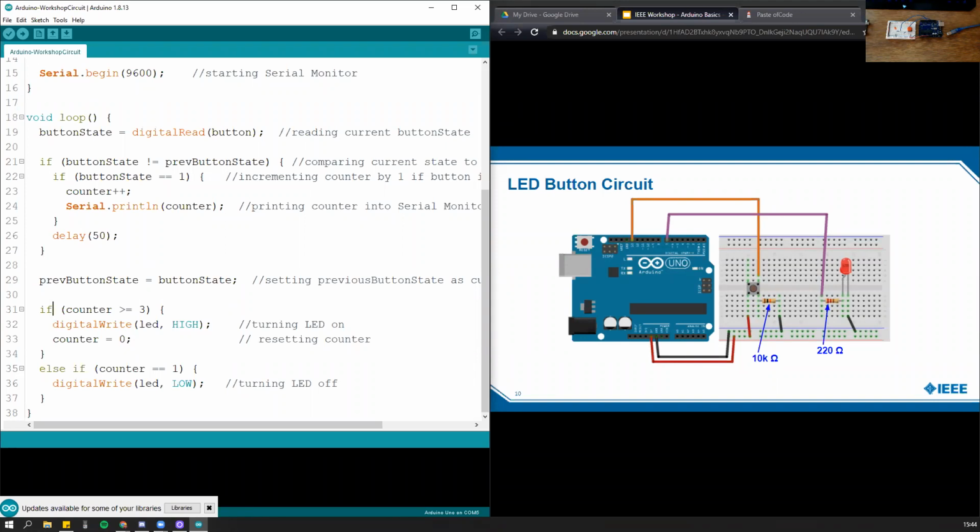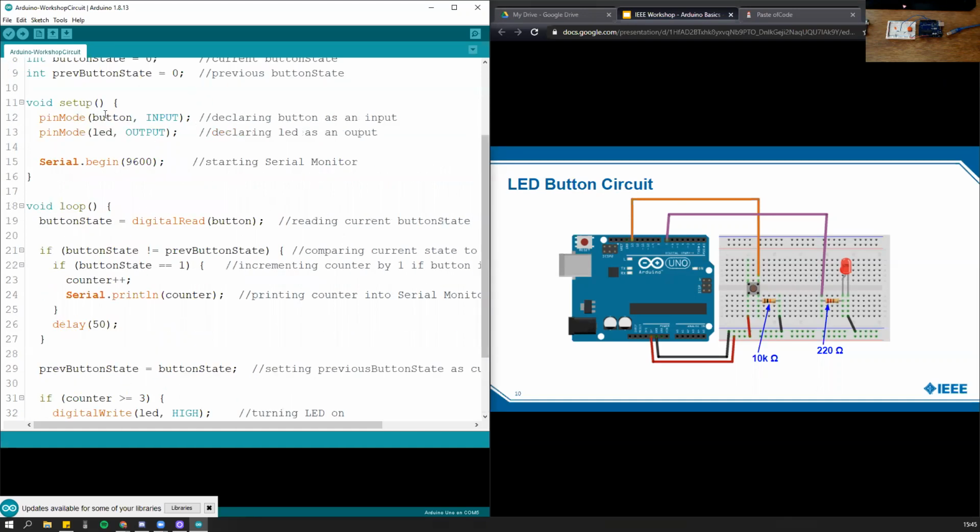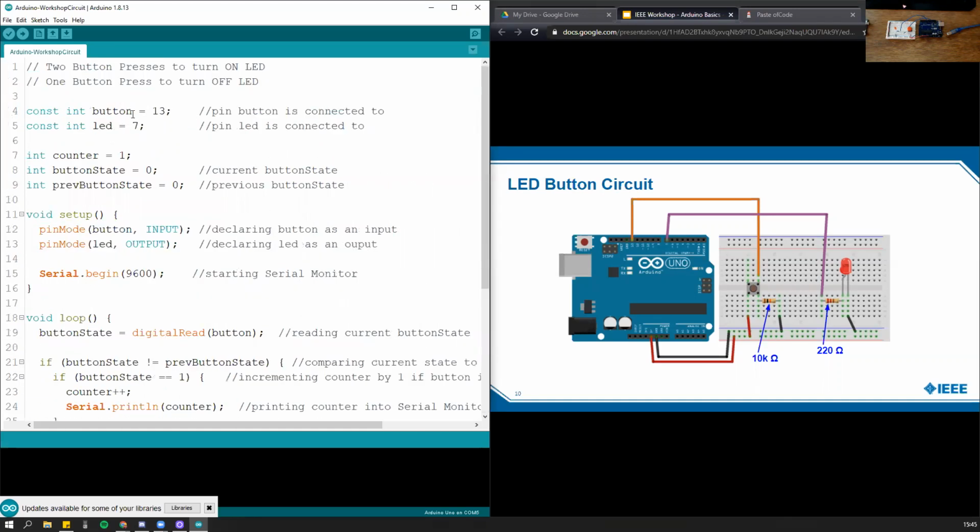Pin 7 is not the PWM, at least not on my board. Pin 6 is PWM, but we're not really utilizing PWM, so it doesn't really matter. Honestly, you can plug it into any pins that you want. You would just have to change the values that they're declared with up here. So if you plug it into a different pin, make sure you change the values that they're connected to up here. When the button is pressed, does it connect all the 4 pins?